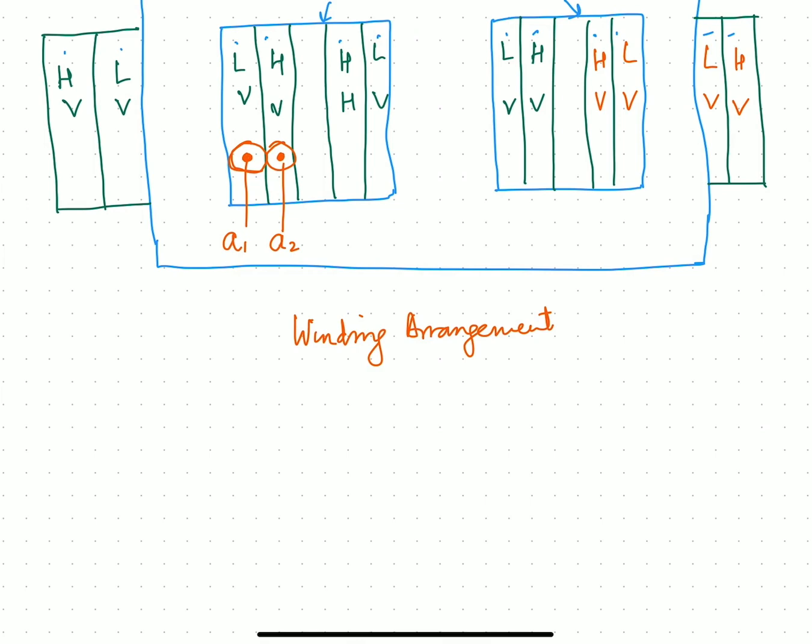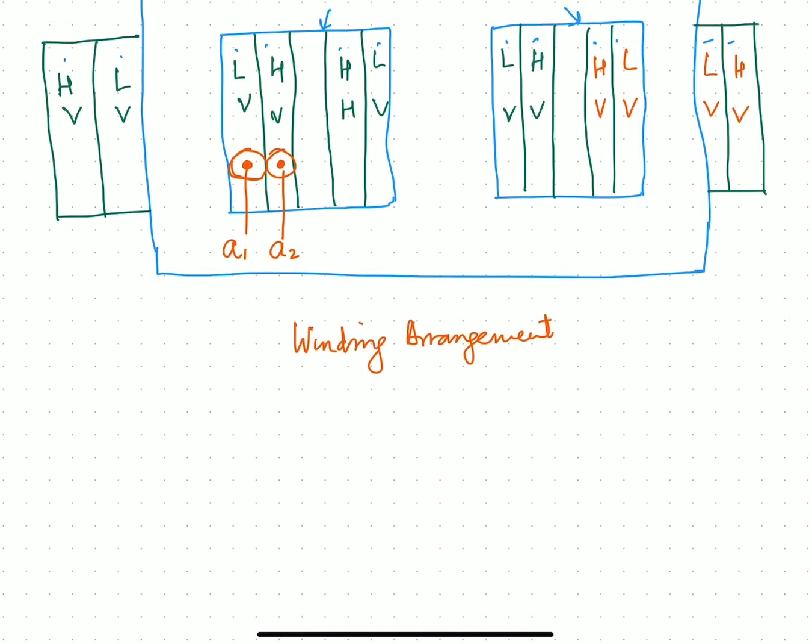So if you recall from the previous discussion about copper area, what should copper area be in this case? Ac is equal to twice Tp ap plus twice Ts as, isn't it? Double than what the area was in case of the single phase transformer, because that had one window only.